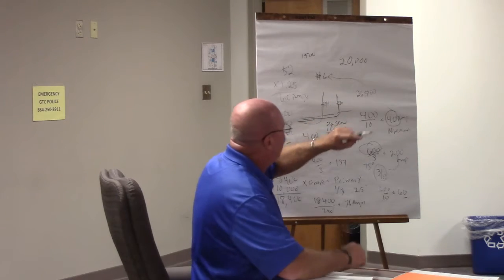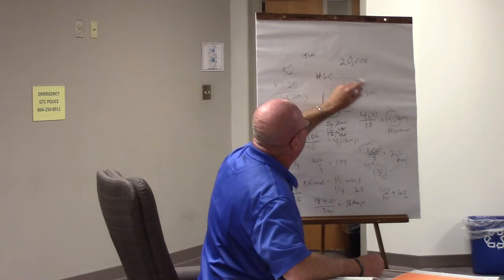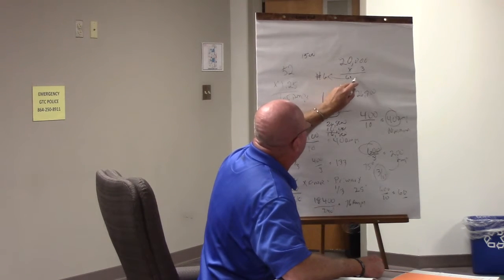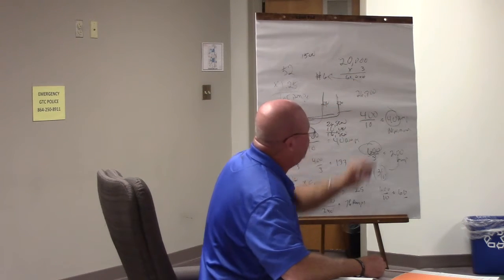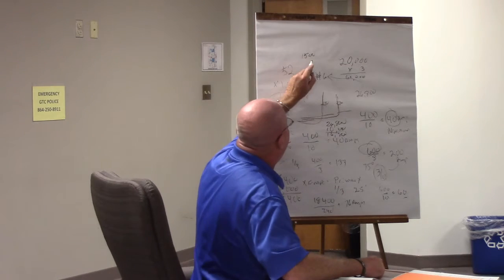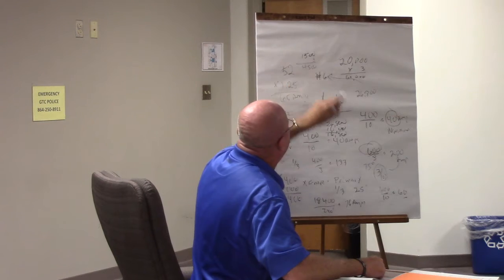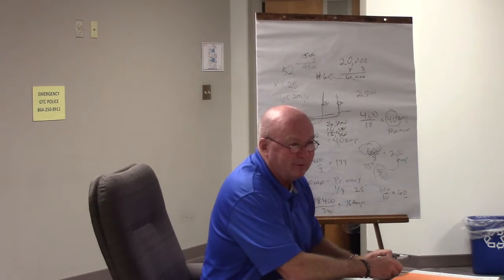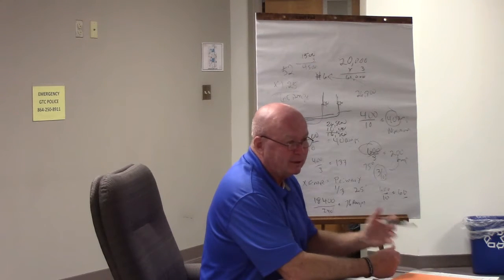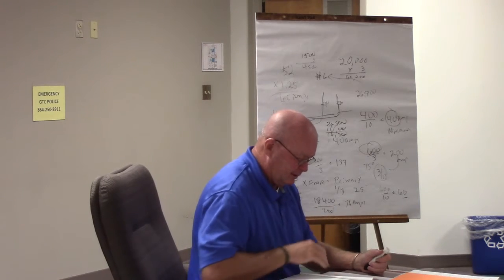Okay. But what we're going to do with that? So 20,000 square foot. That's what it says. So we're going to dwelling. The lighting load for that house would be what? 60,000. James uses a lot of lights. 1,500 square foot house, Ronnie doesn't cut on a whole lot of lights, so it's only 4,500. Big difference, isn't it? But that's what they say the average is, and that's for a house.